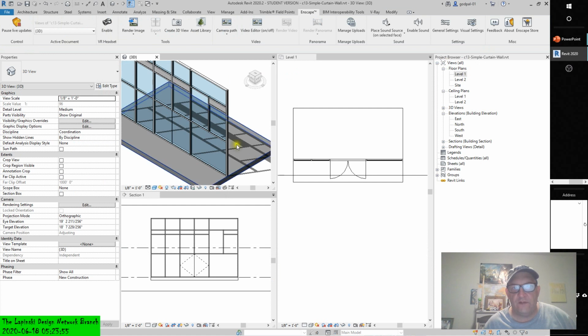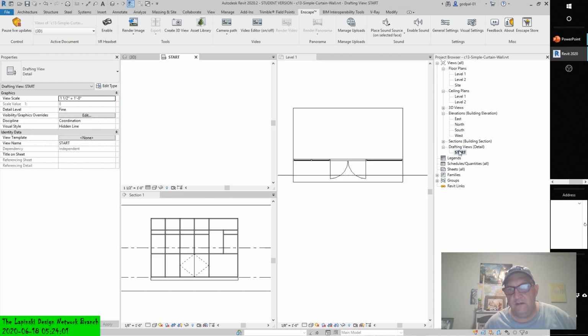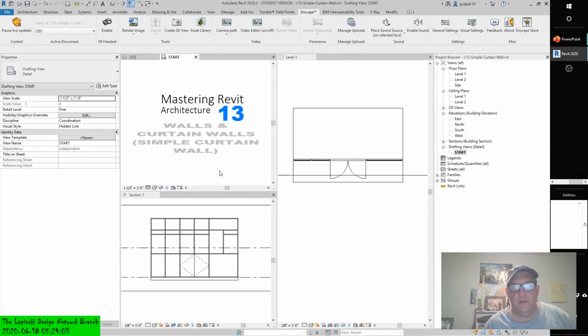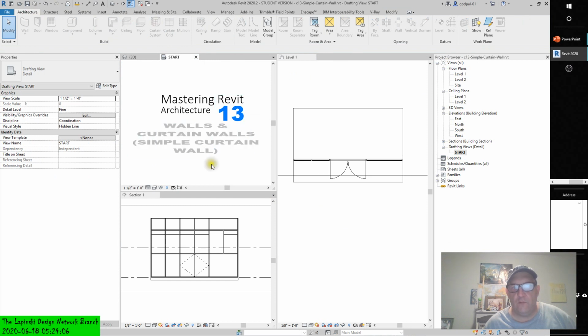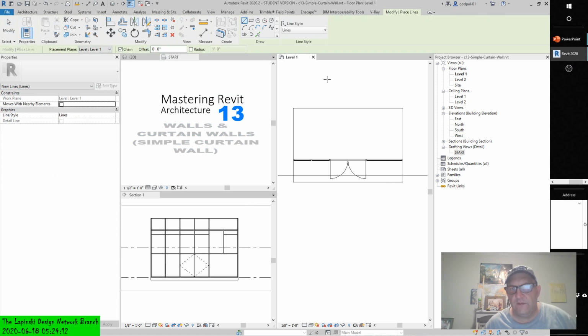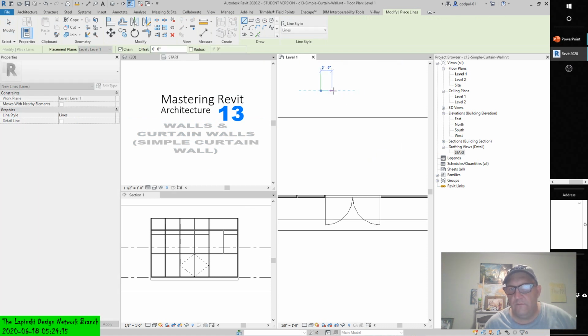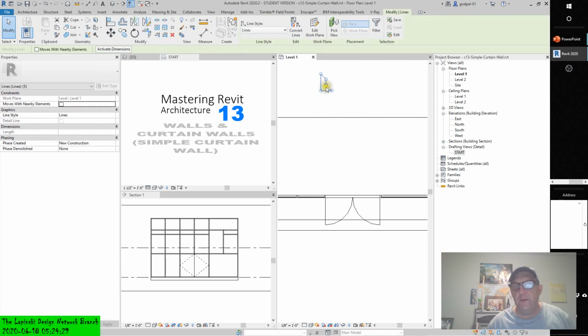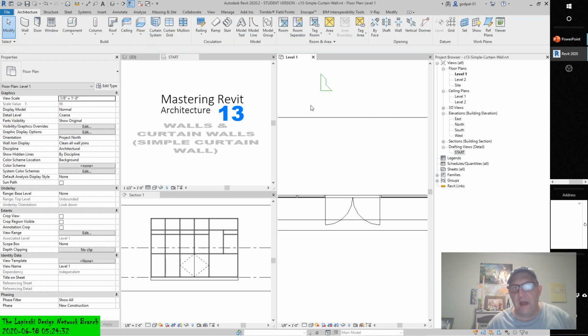If we were to load profiles to change these mullion types, there's no reason why you can't create your own profiles. It goes without saying. If you wanted to create a 2D profile of something to create some complex mullion system, well, there's nothing saying you couldn't create your own 2D profile, save it out, and sweep this around a revolved surface, or revolve it around a surface.